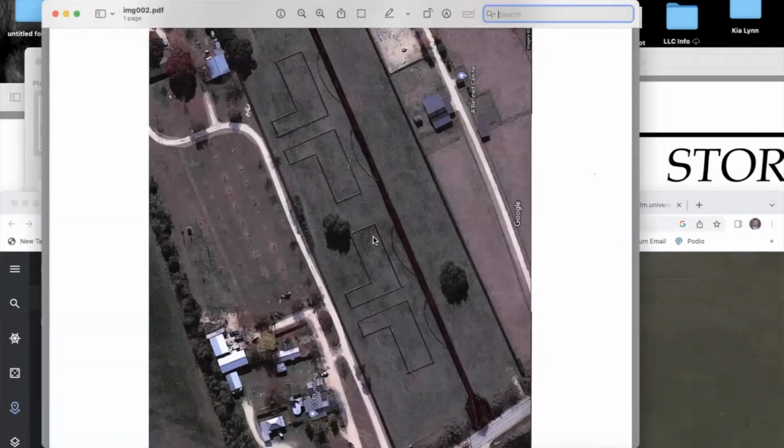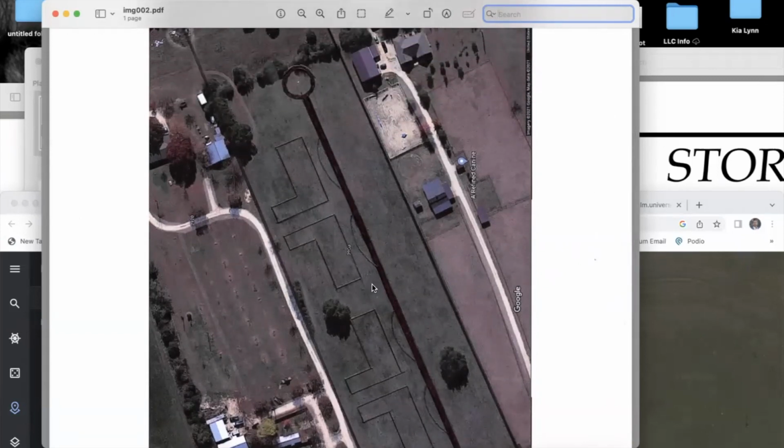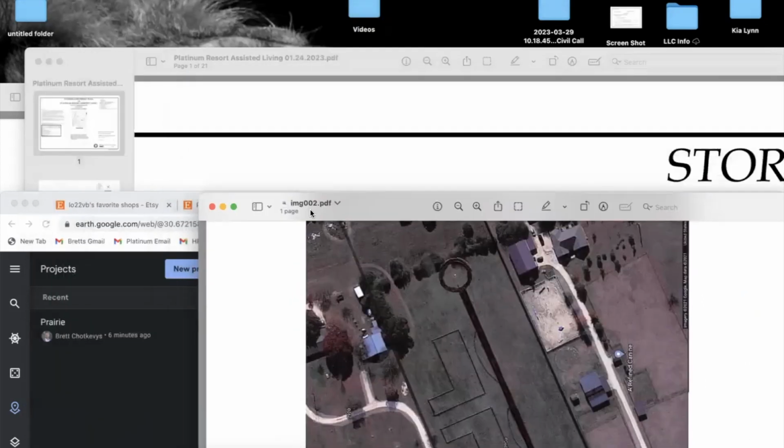So I took this to the fire marshal, right? I had no road behind it. And he said, well, that's great, Brett, but I have to be able to get to every part of the exterior of the building with 200 feet of hose. So a fire hose, right? And he has to stay on the road. So just from here to here, well, let's see, this is 110 feet. And anywhere you position yourself, he can't get a 200-foot hose to back here, right? That was a hard rule for him. So I had to change this, and I'll show you what the next drawing was.